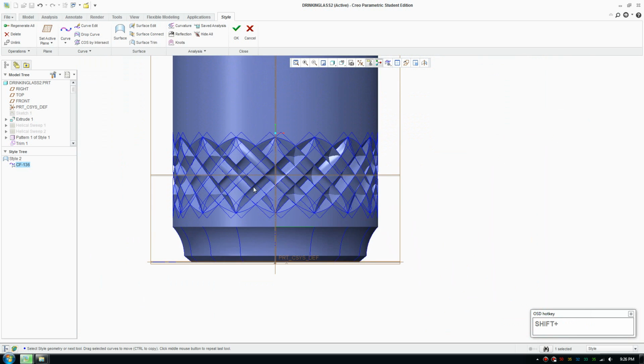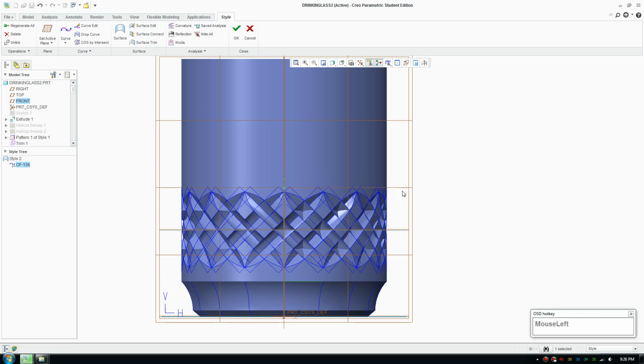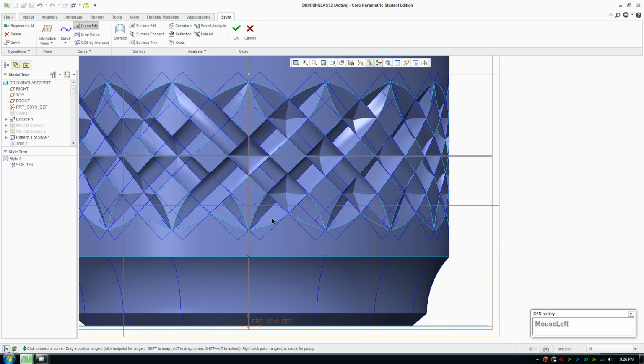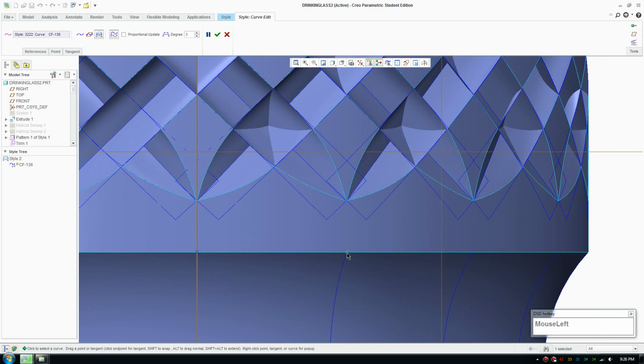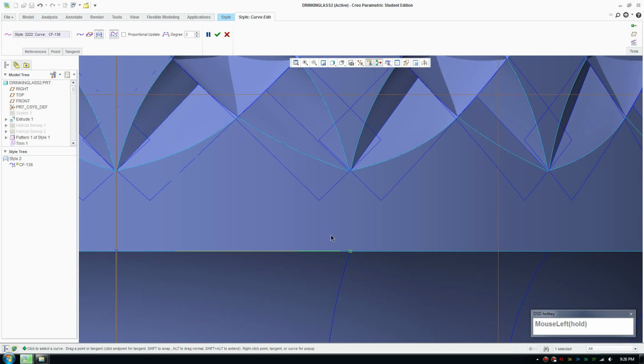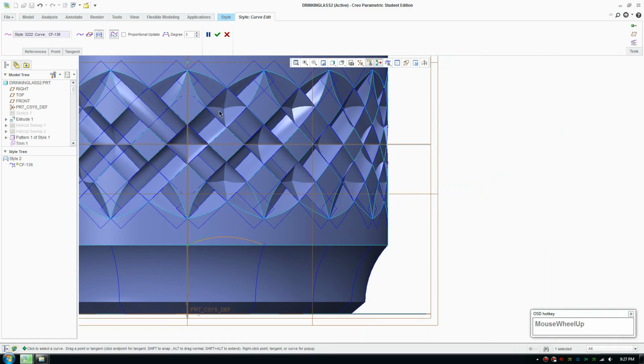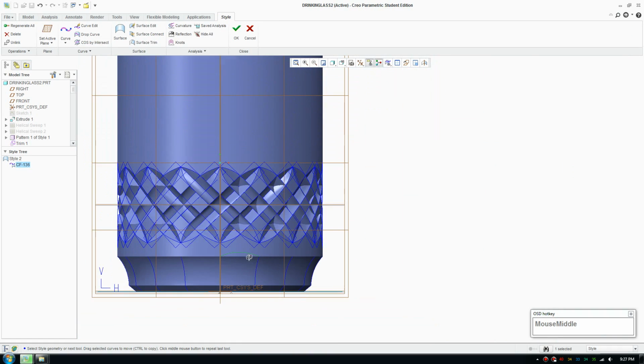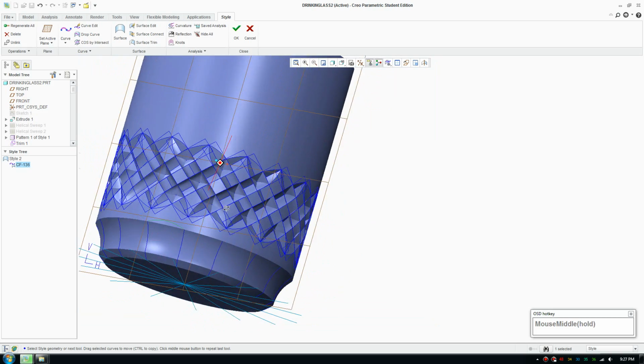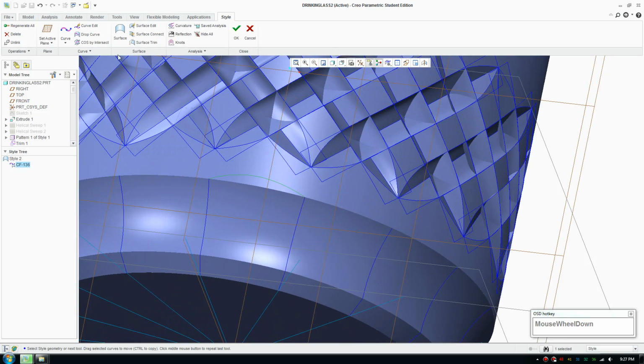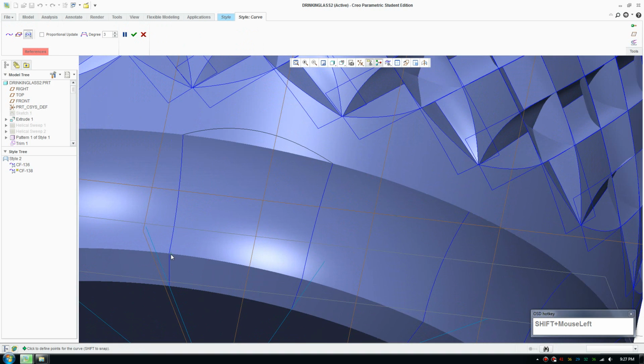Okay, so if you set the active plane to the back plane, when you go edit, select that line that you created, and there should be an anchor line, so you can control the curvature. You can't see it, but if you select the point and drag from the left of it, it should create a curve. So we draw that curve on the surface and we move it up. And I'm going to quickly draw a curve on the bottom here as well.